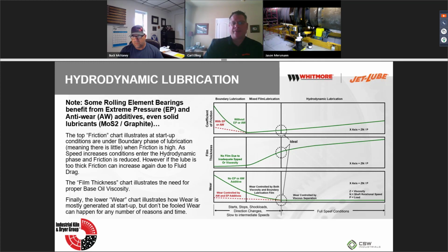Then once you move into mixed film lubrication, it's not as relevant, because you've finally gotten away from the metal-to-metal contact, or the asperities touching one another. In the mixed film, you've got a little bit here and there. And once you achieve hydrodynamic lubrication, the EP or anti-wear is really not all that important. That's where fluid strength and the thickness, or the viscosity, of the oil comes into play.